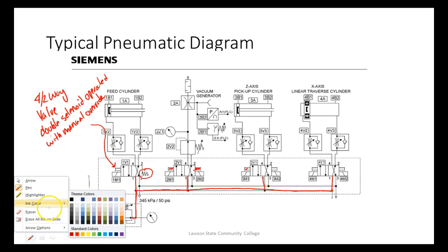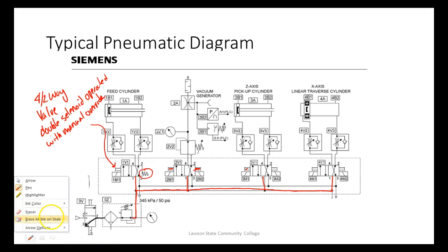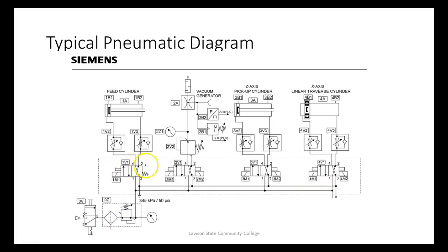Any questions? Everybody okay so far? And what you have to do, of course, in your head, is when this solenoid operates, you got a picture of this whole valve moving in that direction. So this block moves against the spring, and then this block right here lines up. That's what you got to do.